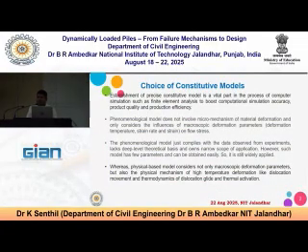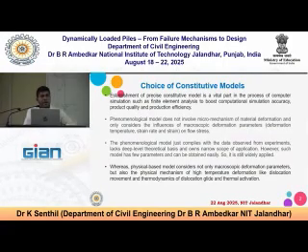This is a simple constitutive model. Now whatever you want to add, you can add. So you couple it and your material model will be strengthened by adding the strain rate, stress rate, state of stress, triaxiality, temperature, right? So you can improve the models.